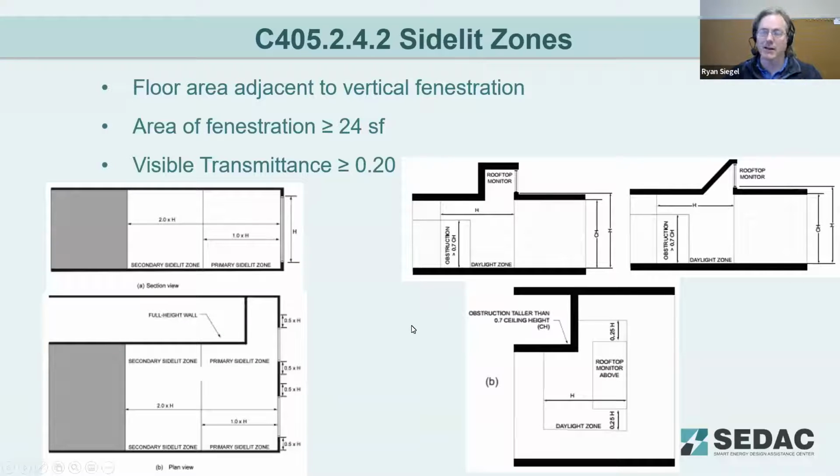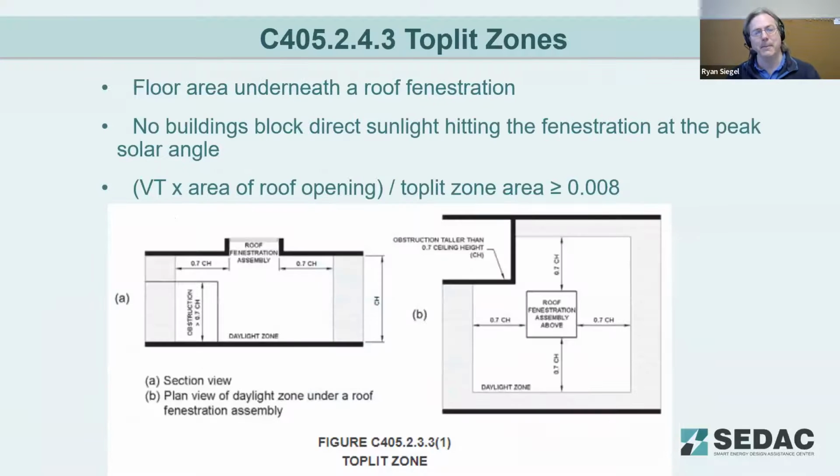Again, going back to that, you have to know what 40% of that lighting allowance for that particular area is. So it's extremely helpful if somewhere on the prints, particularly with the dashed line or the shaded area, you go ahead and call out what that square footage is, because that makes it a lot easier later.